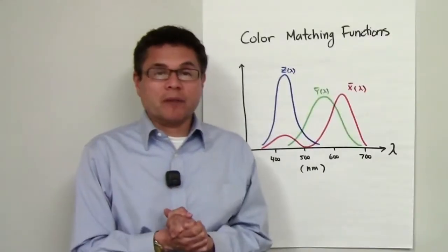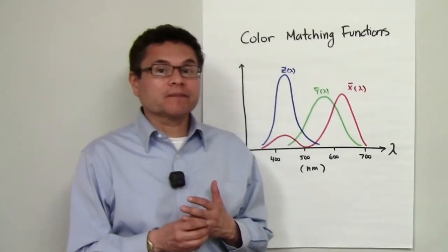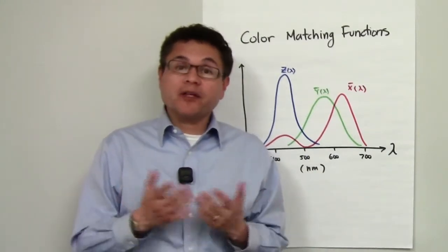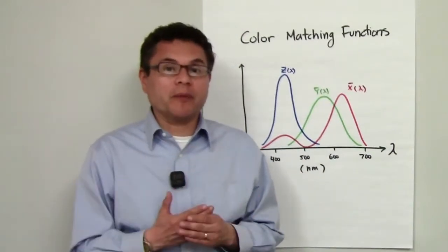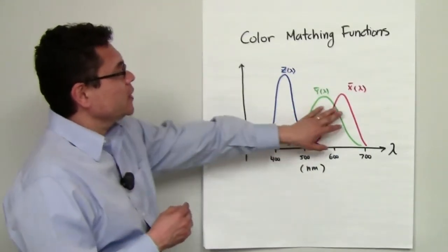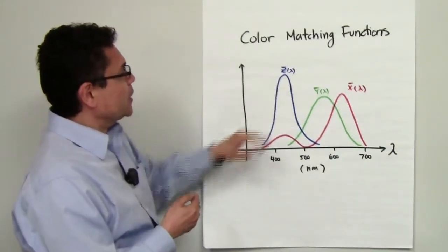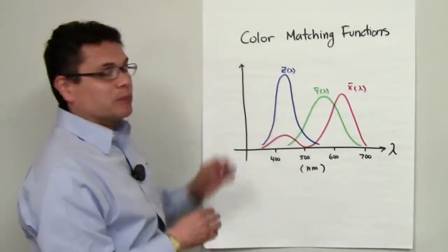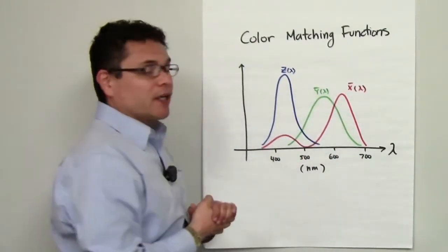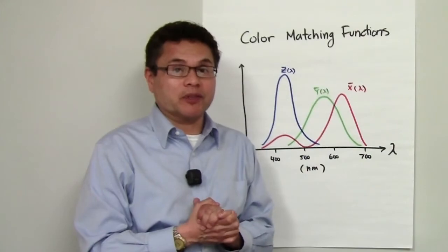Let's first start talking about the sensitivity of the human eye to color primaries. You could represent any image in 3 color primaries, and the sensitivity of the human eye is not equal to each of those primaries. In this color matching function diagram, you could see the response of the human eye to the green, the red, and the blue components of a primary. Here, for instance, you could see very easily that it requires a lot more power to represent blue colors than it takes to represent green or red. This will be very important when we talk later about image representation and especially subsampling of images.